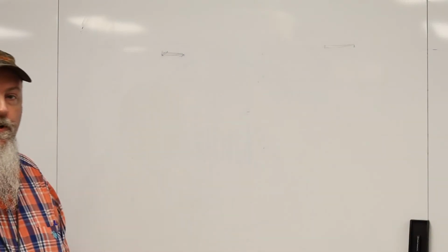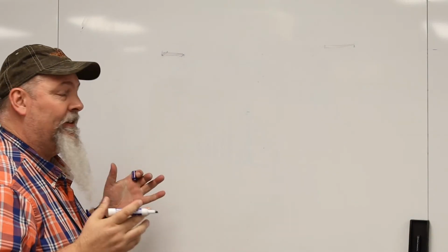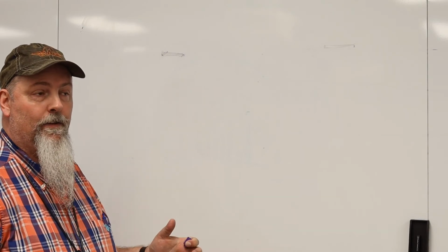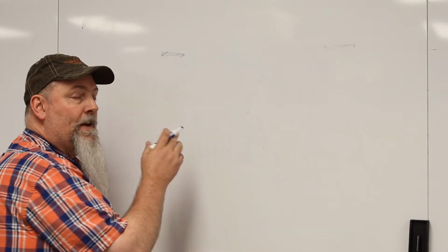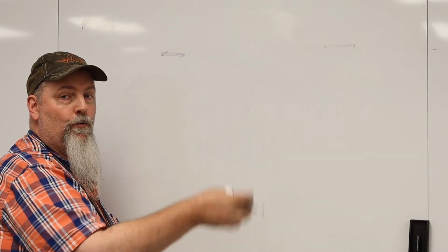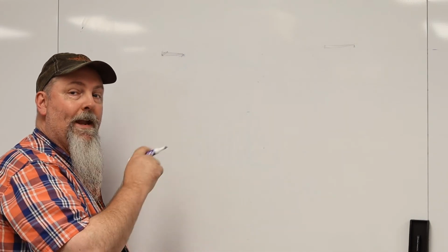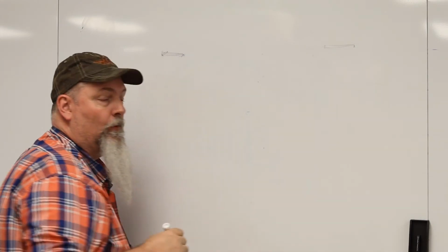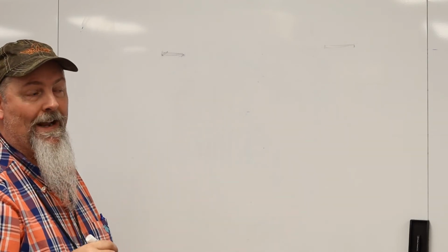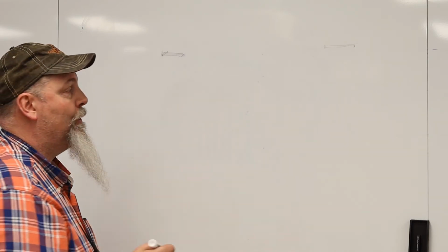Now a 2 of 2 taken once. It's the same idea, but instead of needing one in each of the 2 channels, I just need both in any one channel. So let's do an energized to actuate, 2 out of 2 once.